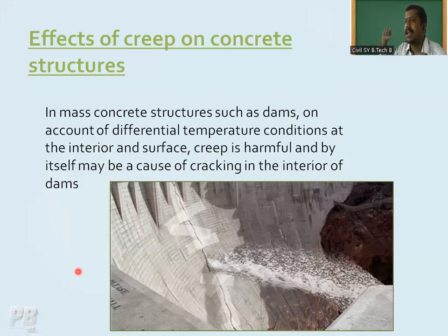And I had a funny experience. I showed this diagram to somebody, and they told me, sir, this is the drain, and through that drain the water is percolating. Okay, it is not the drain, it's a big crack which was there on the exterior wall of the dam. So you need to understand which one is the crack and which one is the provision made for that particular concrete dam. So see, creep is very dangerous.